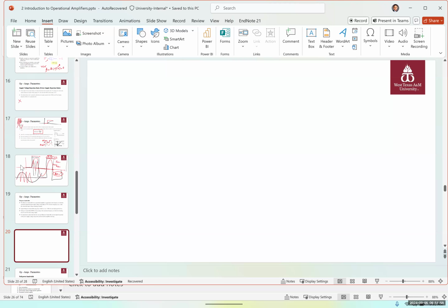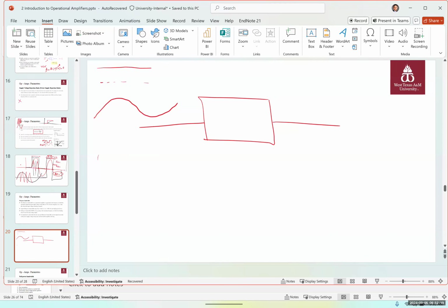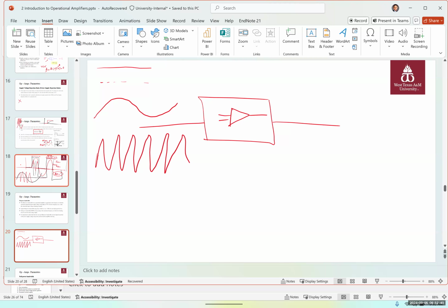Okay. So frequency response means if I have a circuit, doesn't matter what circuit I have, and I give it a very small frequency, low frequency, and I increase that frequency gradually. So imagine I'm starting from DC, which has a frequency of 0, and I slowly increase the frequency. I want to see how fast this system can respond to this frequency. Imagine that this is, for example, an op amp or a transistor or anything.